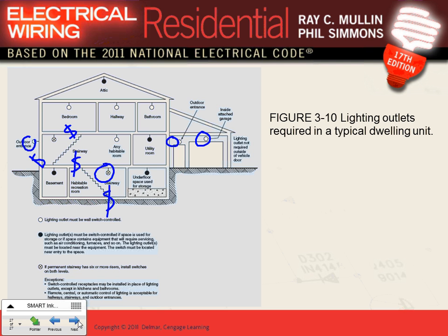You understand what I mean? Instead of having a light there, you plug a light into an outlet, and you switch the outlet. There's nothing worse than buying a house that doesn't have any ceiling lights. I hate that. Mine has the same thing. But a switched outlet can act as your lighting outlet, except in the kitchen and the bathroom and laundry.